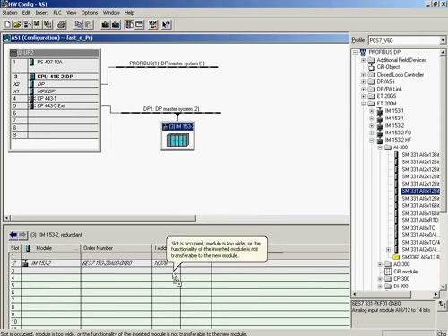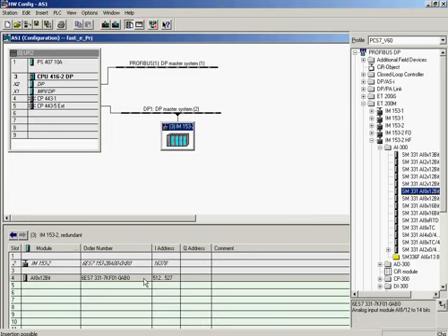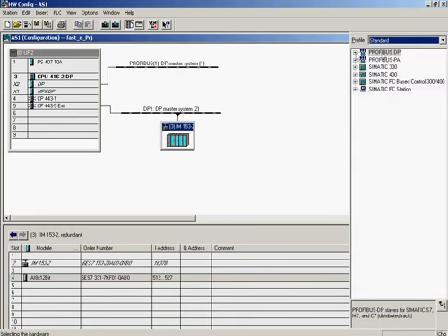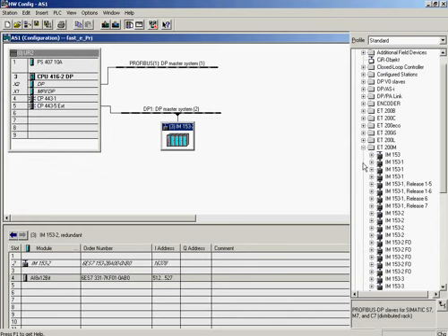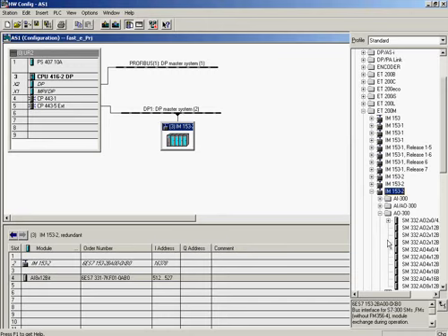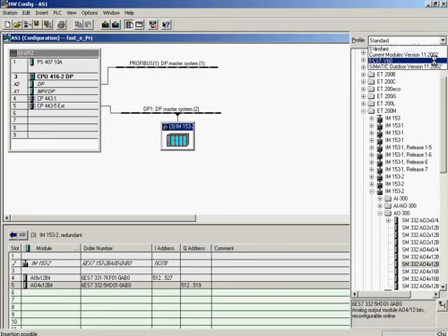This module is included in the catalog of hardware that is optimized for use with PCS7 v60. The analog output module is plugged into slot 5. This module is included in the standard hardware catalog. In this profile, you can find all modules that are supported by and are compatible with SIMATIC PCS7. However, we recommend that you work with the PCS7 v60 catalog, since it contains the subset of available hardware modules that are optimized for use with PCS7 v60, and therefore enables you to work more efficiently.